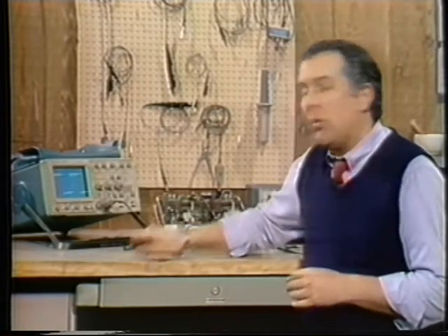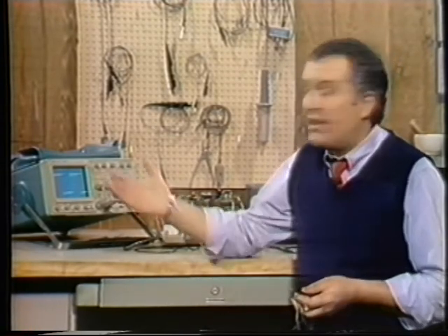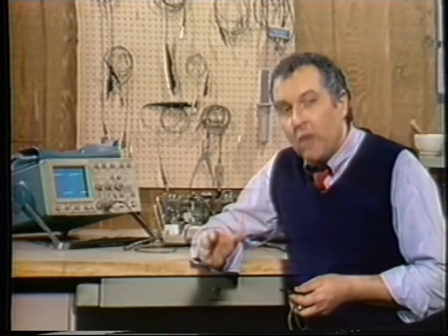That's important. Oscilloscopes and passive probes should be carefully matched in bandwidth. For example, this is a 100 megahertz passive probe. It's designed to be used with a 100 megahertz oscilloscope. Now, if I insisted on using it with a 350 megahertz scope and viewed a fast rise time signal, the aberrations would be increased because the lower bandwidth probe was not designed to control the high frequency components of the faster input signal. Much like the grain of a photograph would increase as we used higher magnifications.